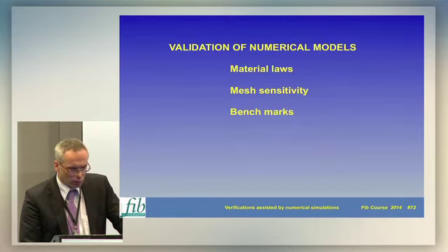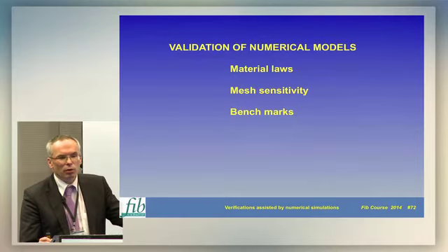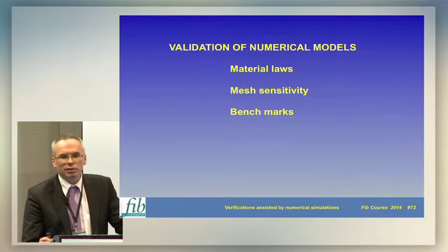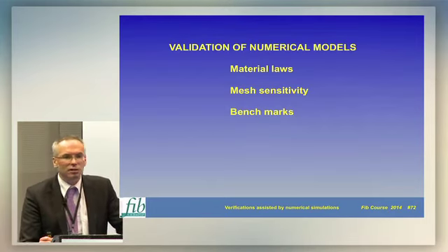So, when validating numerical models, one should divide it into, let's say, three levels. The first thing is to be able to reproduce material tests: the compression test, tension test, and triaxial tests.